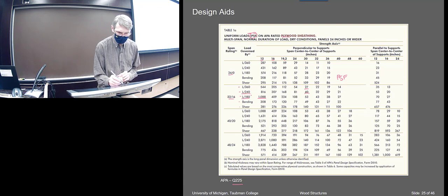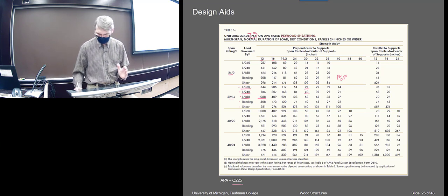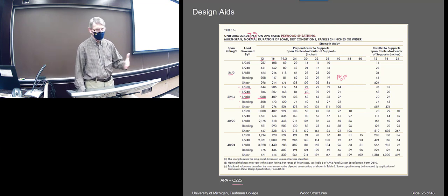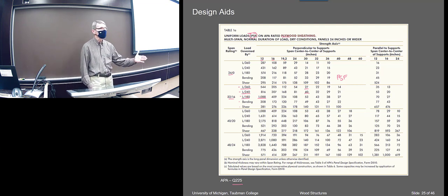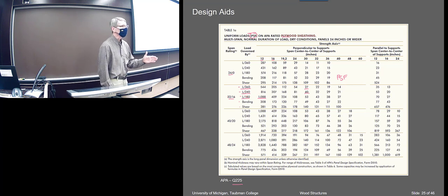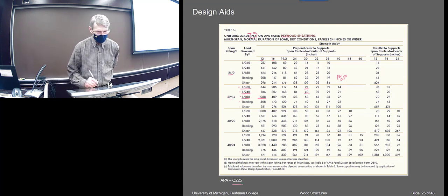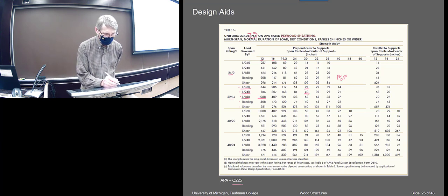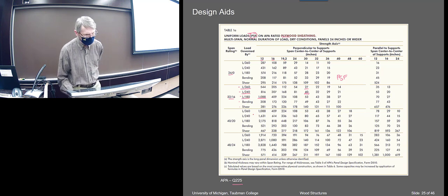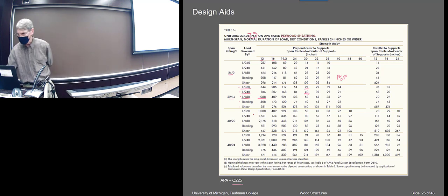If you go with that 40 psf, you're going to feel the bounce probably at, I mean, L over 240, I think you almost feel that bounce, don't you? This one's the stiffer one. This used to be the norm for residential floors or live load loading, right? That's where you feel that bounce. So, yeah, this is certainly strong enough, but it might be a little bit bouncy at that 40.